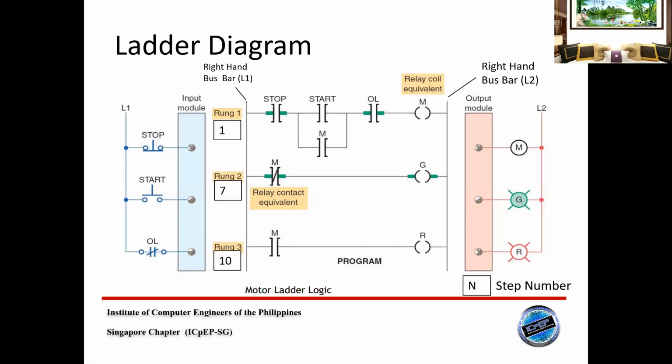So the PLC resolves the logic of the ladder diagram rung by rung, from top to bottom. So the execution will be top to bottom. Usually all the outputs are updated based on the status of the internal register. Then the input states are checked and the corresponding registers are updated. This process runs in an endless cycle, so it will run endlessly.